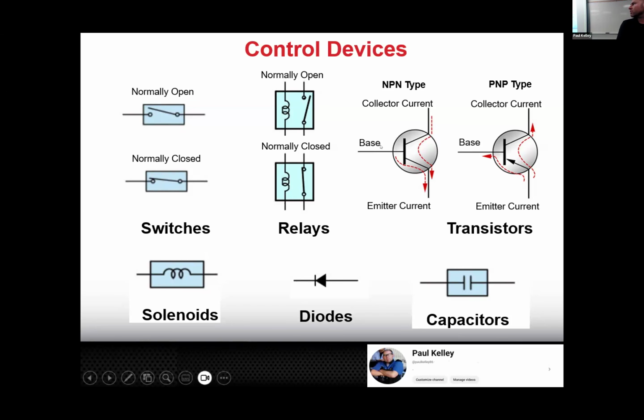So if we were to have, let's say, we're trying to flow electrons through here, that would be the high current. This could power a fuel pump. We have 12 volts, we send it into this transistor, and if the transistor is activated, it will send 12 volts to the fuel pump and run the pump. But how do we control the transistor? Well, it's all about what it gets right here on the base.